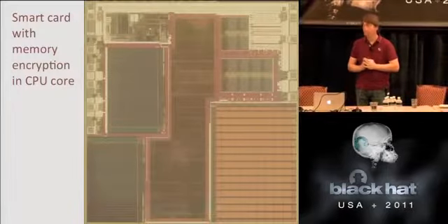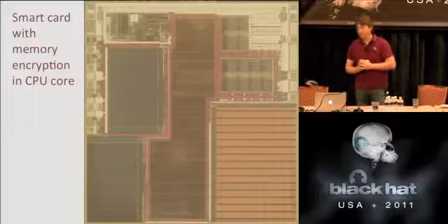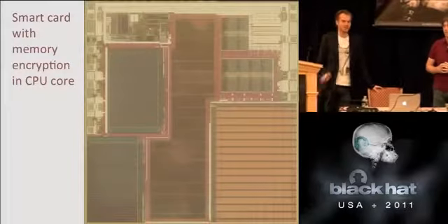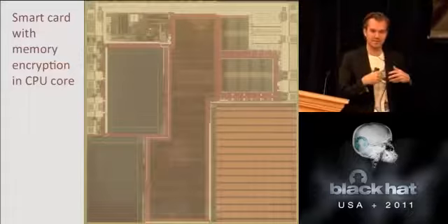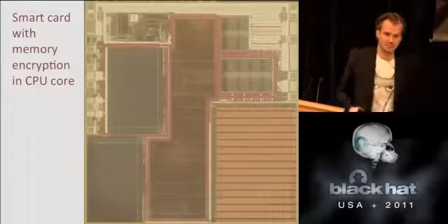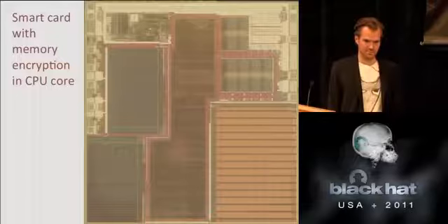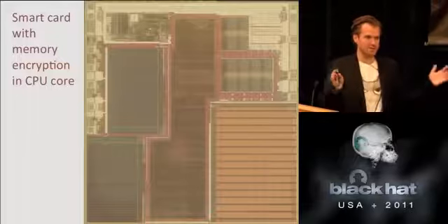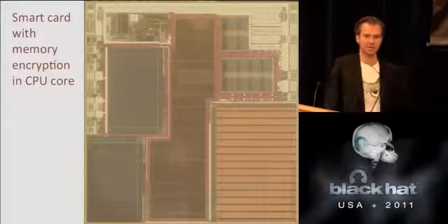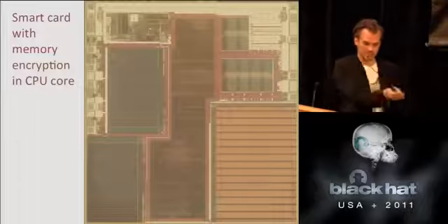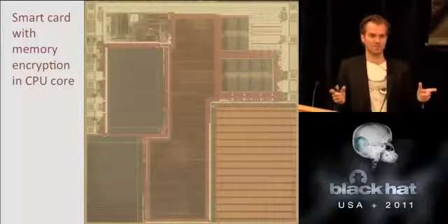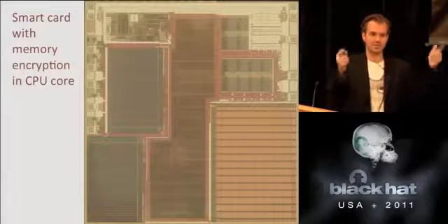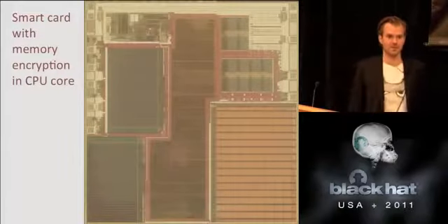But generally, I guess a good generic strategy would be to find the elements on the chip that take in the data. That would be the instruction latches. Find 8 or 16, maybe 32 of them, depending on the architecture. And if you found on this chip 8 same flip-flops, then you have a good chance that the inputs to those are the relevant ones.